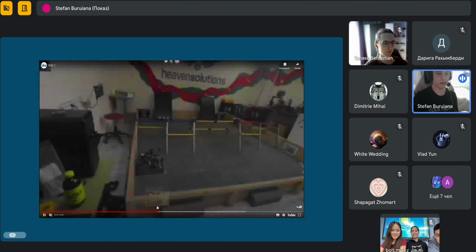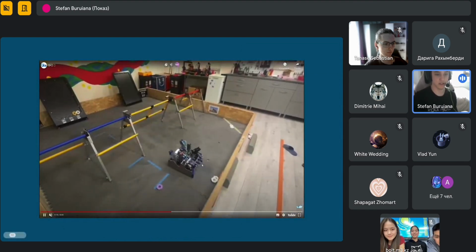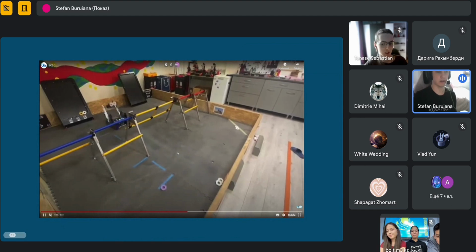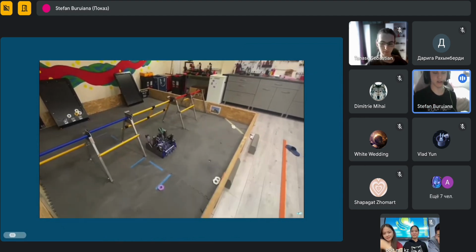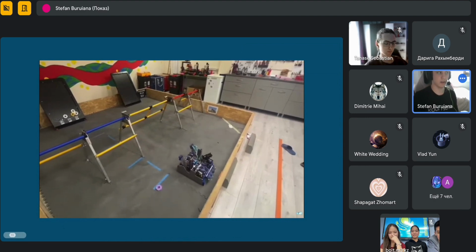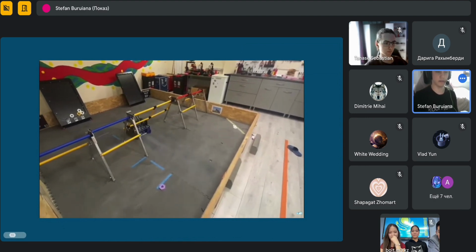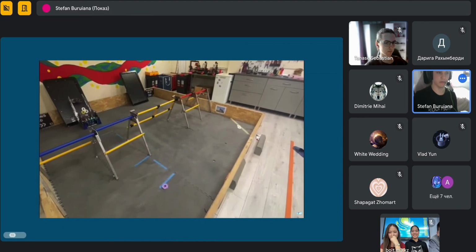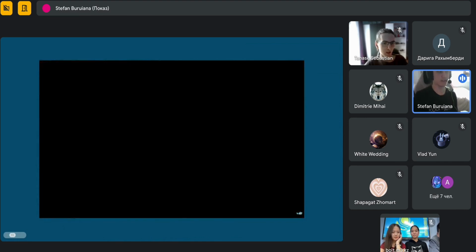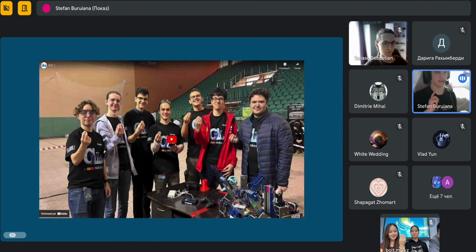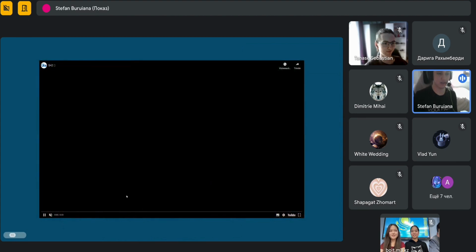And the outtake we landed with is a damper design, because we found a really innovative way to use rubber bands and micro servos to have a really lightweight outtake that is very easy on the micro servos. Actually, we only broke one micro servo after switching to this, which is the thing that we wanted to avoid. We didn't want to break any micro servos doing this.